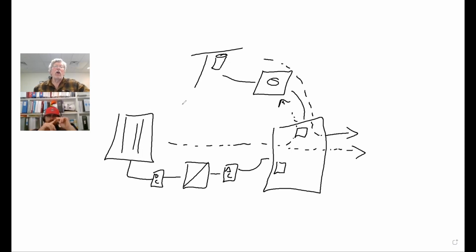So at all times, the amount of power flowing through an inverter is based on the size of the array, because whatever the array is generating is going to flow through the inverter. It is divorced from the load; it has nothing to do with the load. So the concepts are completely different for a grid-tied system versus a standalone. With a standalone, 100% of what goes through the inverter is dictated by the load. With a grid-tied system, 100% of what goes through is dictated by the array.